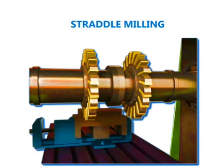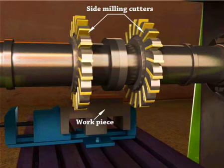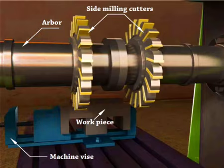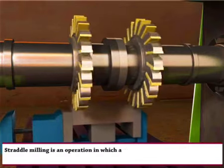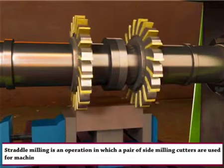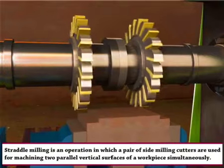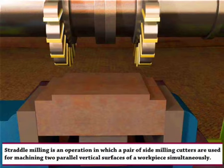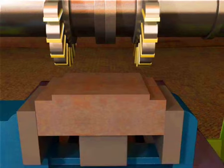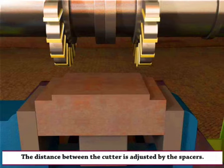Straddle milling. Workpiece. Side milling cutters. Arbor. Machine vise. Straddle milling is an operation in which a pair of side milling cutters is used for machining two parallel vertical surfaces of a workpiece simultaneously. The distance between the cutters is adjusted by the spacers.